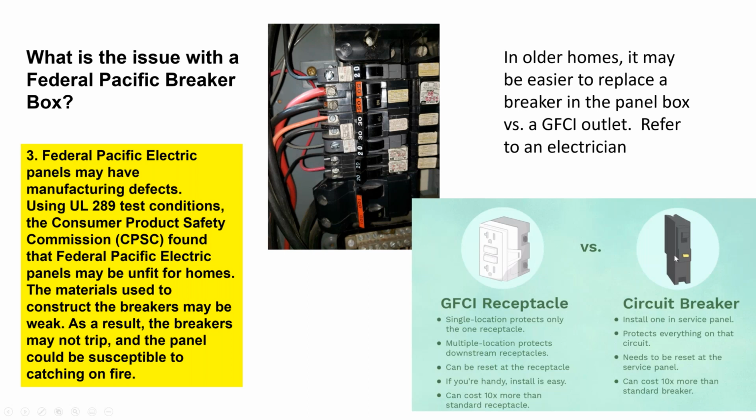All right. To replace one of these is not hard. You take the cover off, you unscrew the outlet, you put the new outlet in there, put the panel cover on there, and you're done. It's a $15 fix. Don't let it freak people out. It's not a big deal. The circuit breakers are a little more expensive and actually are required now in new construction homes, that the panel boxes have GFI breakers installed here. All right. They trip often. All right.